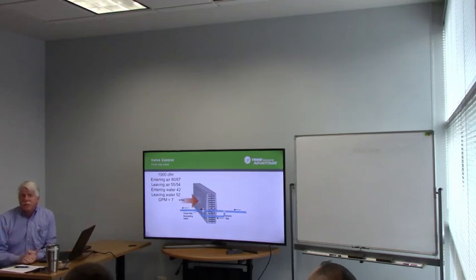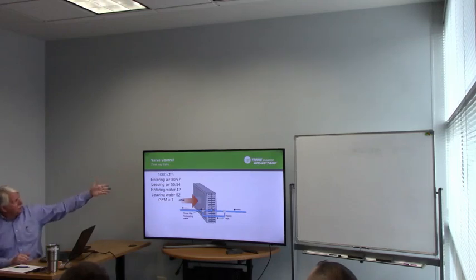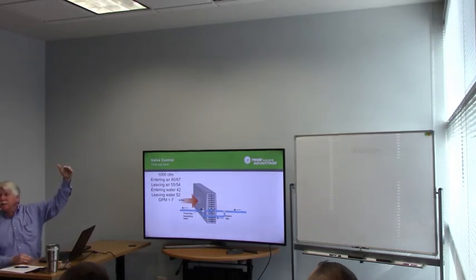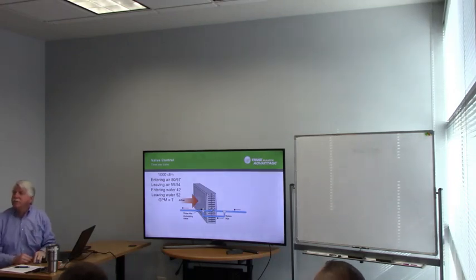And one of the places you guys will see this a lot is our air handlers are always designed around some amount of outside air. And usually it's in the 15 to 25% range of outside air. Now, this unit is calculated for Chicago because we normally have about 80 degree mixed air temperature when it's 95 degrees outside and we're bringing in some outside air. The temperature in the mixing box will be about 80 degrees.